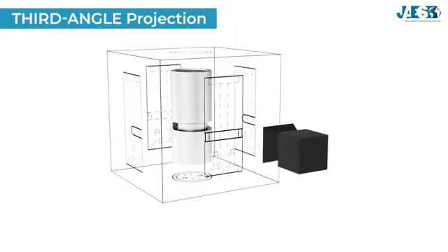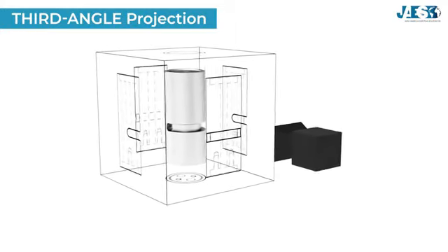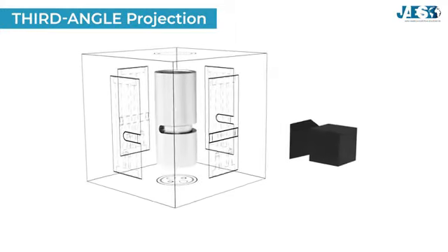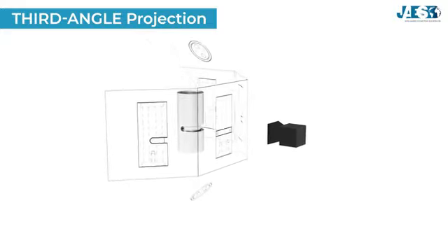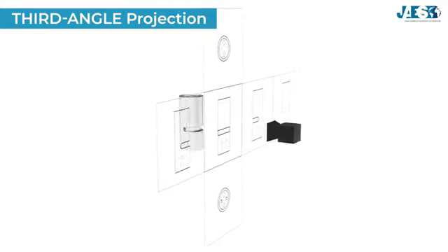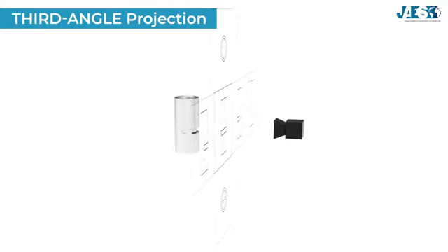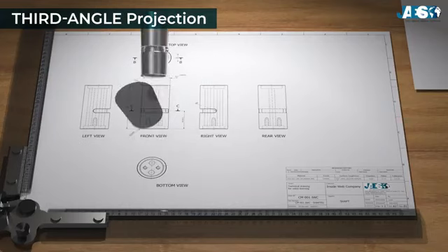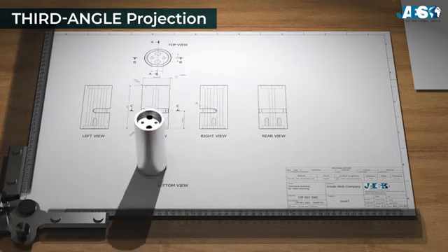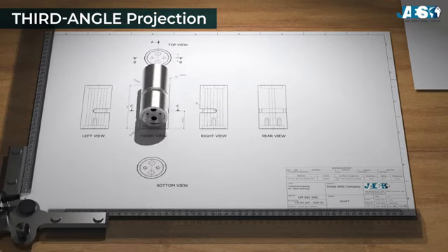In contrast with the third angle projection, it is the projection planes that are between the observer and the object. Imagining the cube surrounding the object, each view is projected onto the outer walls of the cube to then be unfolded. For simplicity, starting from the front view, we have its right view, top view above, bottom view below, etc. The exact opposite of the first angle projection.